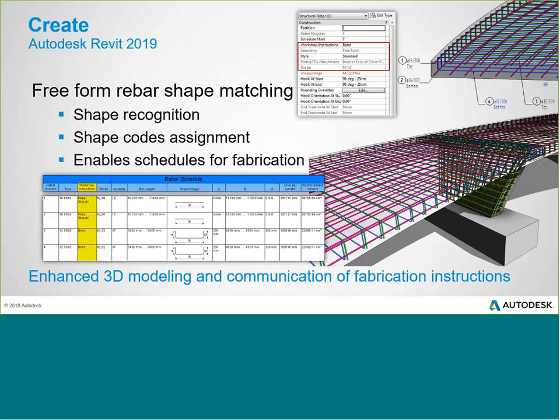Some improvements to rebar shapes. There's shape recognition and there's shape codes assigned to the different shapes. So it allows for scheduling of the actual fabricated rebar. I don't know how many people are utilizing these tools, but in the past, they were pretty basic and pretty tough to deal with.